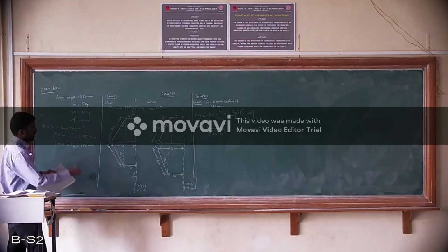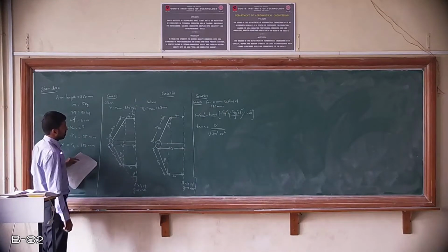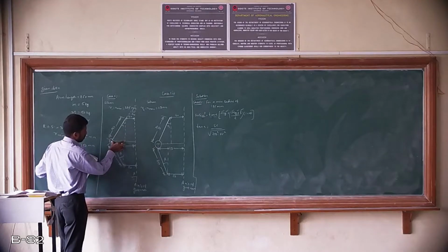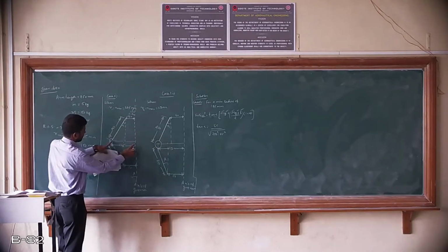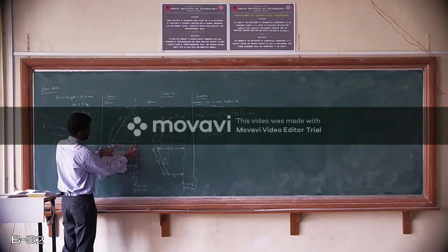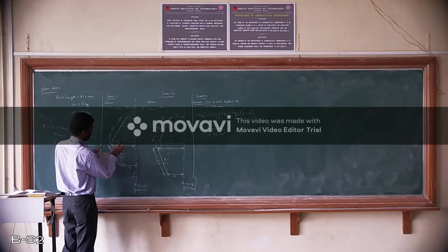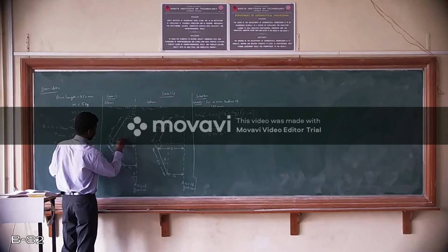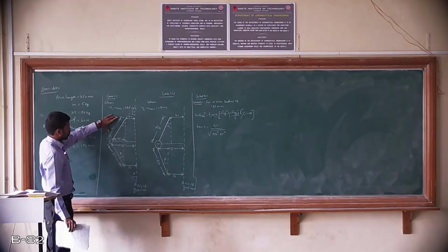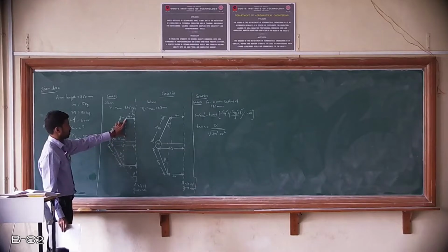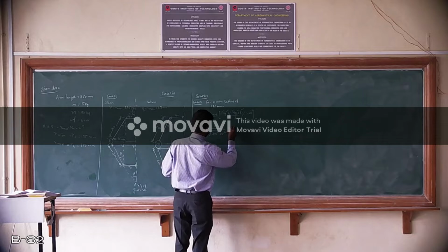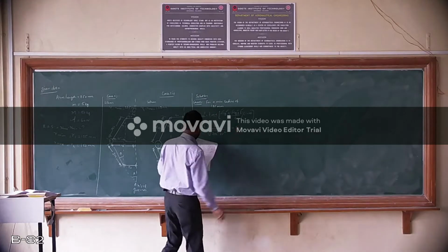What I have done is I have used the equation of tan alpha: opposite divided by adjacent. This is my opposite. This entire length is 125, I need only this length, and the length 40 is known. So 125 minus 40 gives this value as 85. The adjacent is this one, that is under root of 250 square minus 85 square, which gives us tan alpha, and I get the value of tan alpha as 0.362.